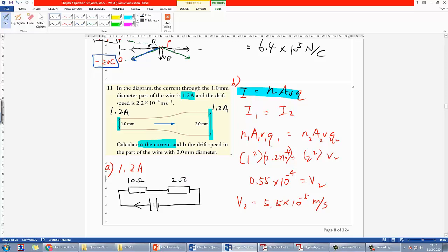When you say resistor, you can imagine that they have a different radius or different cross-sectional area of wire passing through it. So if you put an ammeter here, or here, or here, they all measure the same current no matter what. This is for sure something you could accept in year 10: this is a series circuit, there's only one path, so the current must be the same.